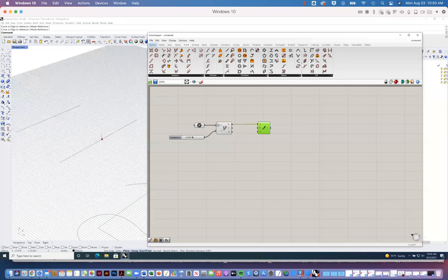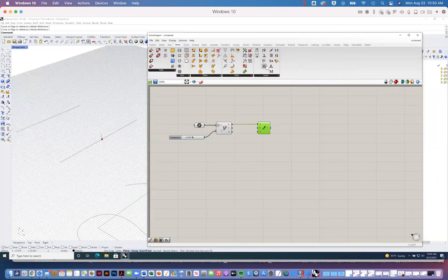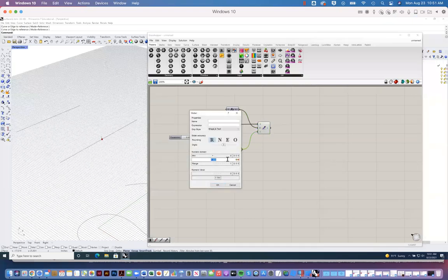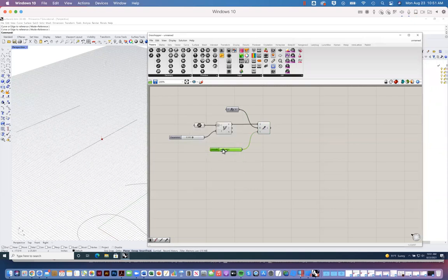The direction I'll use, let's see, the z-axis in the world Cartesian coordinate system here. And for length, I'm gonna make that a variable, right? So again, here's another parameter I can change. It's a variable parameter. I can use a slide bar and adjust the minimum and maximum. There we go. Oh yeah, I can make that as tall as I want, darn it.